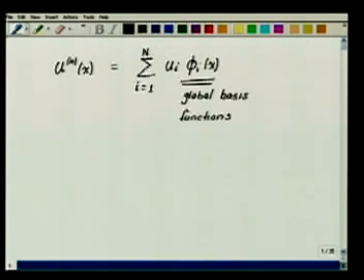So we choose our phi's differently. There's no restriction on choosing the phi to be of a particular type or of a different type. It depends on what is the particular application for which we are using this representation. That is going to decide what kind of phi's we are going to use. So in the Rayleigh-Ritz method, we had shown that one choice of phi's was the polynomial type. That is, the phi was a polynomial defined over the whole domain.